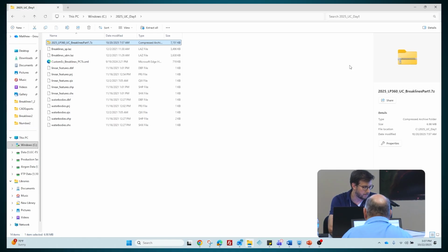We'll see if we have time to cover this, but if you're trying to digitize a stream, you start off with digitizing the center line of the stream, and that conflation is called downstream constraint. It basically forces the line to go downstream, so it will actually burn through the last data. So not only is it conflating to the surface or the minimum value or max, but there's also some intelligence to how this is run, to try to conform to the feature you're trying to collect.